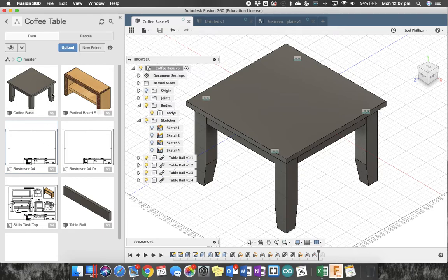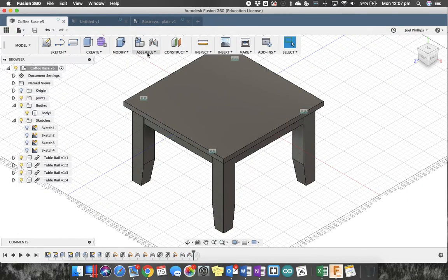You can move that into your Year 12 major project or whatever you like, but once you've done that, you'll be able to use it as drawing view. One problem we have is that by default it chooses first angle rather than third angle in the drawing, which for the coffee table doesn't matter too much, but it means that when we look at the projected view above, it shows the bottom of the coffee table.